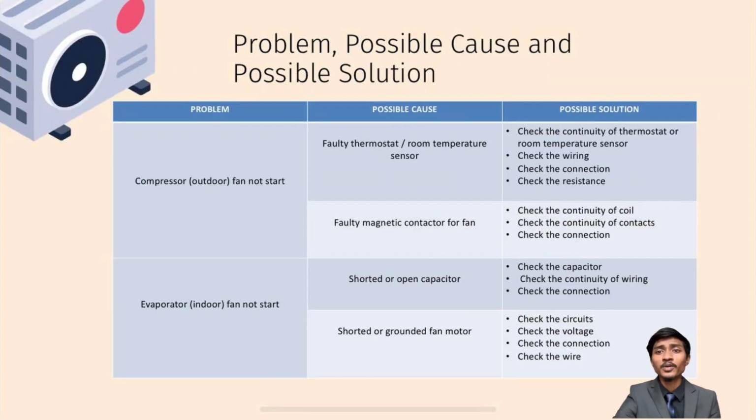For the problem number 3 is compressor outdoor fan not start. Possible cause for this problem is faulty thermostat or room temperature sensor, and faulty magnetic contactor for fan.